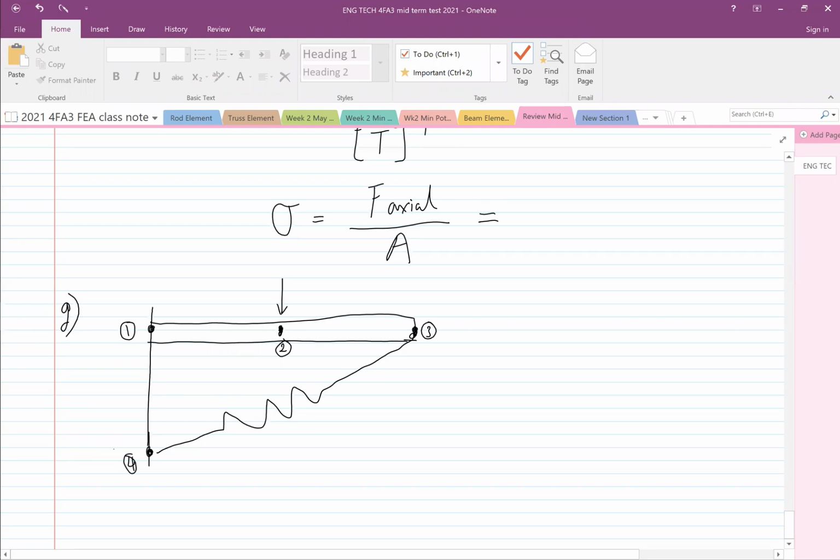Did you work on ANSYS lab 2? When the element's too coarse, you cannot detect very good stress values. So that's why locally you put more nodes around the affected area to get more information from it.